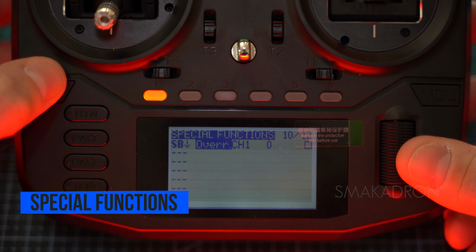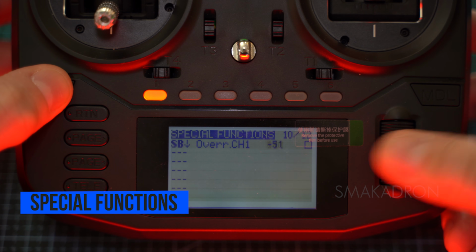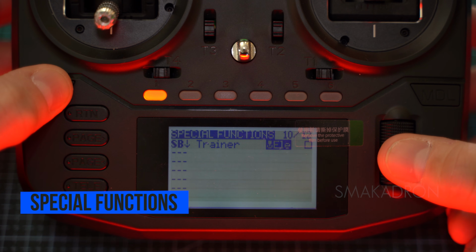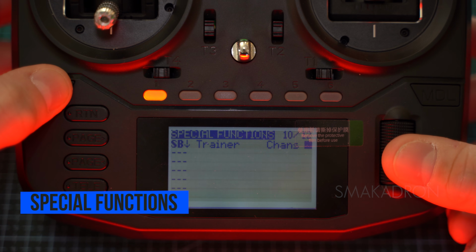Override. Overrides the value of a specified channel with a set value. Next is the channel to override. Value, the value to replace the normal channel value, ranges from -100 to +100. It's actually hard to come up with something interesting for this function for our drone. Trainer. Enables trainer mode. Value defines which control elements will be passed to the student. Options: sticks, all sticks; rudder, elevator, throttle, aileron; chans, all channels. The main thing is not to forget to check the box to activate the new function after creating it.